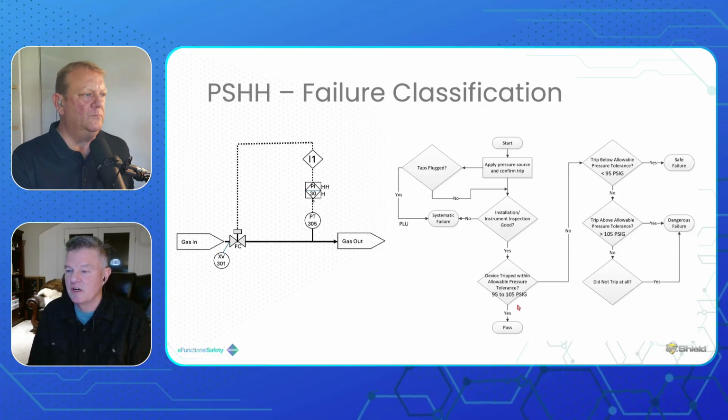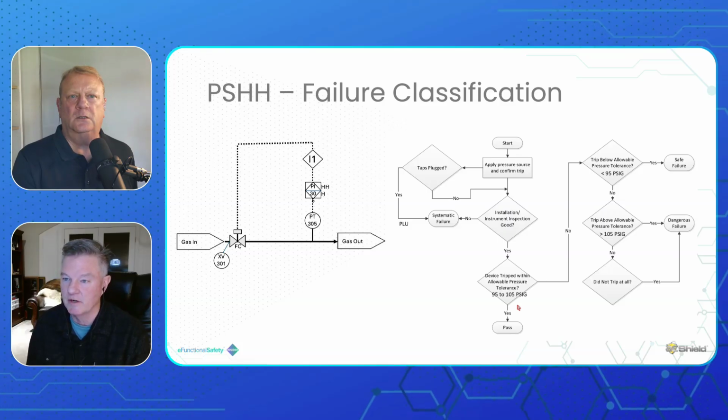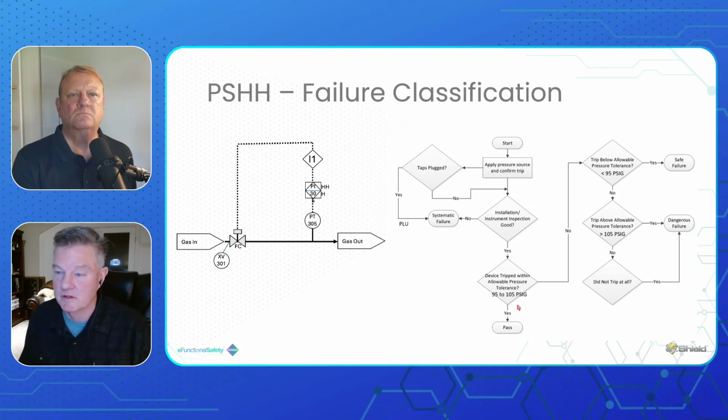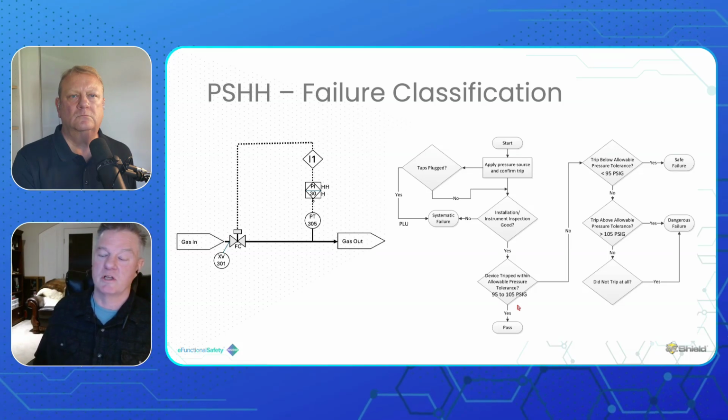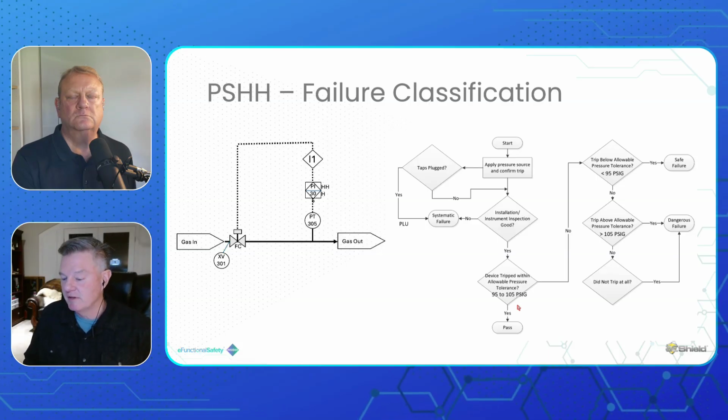So this is classification. Think of a valve, overly simplistic: what is it? It's got to close fast enough, right? If it's a high pressure close valve and the response time is 10 seconds, if it closes faster than 10 seconds, it passed. If it closed slower than 10 seconds, it failed. It's that simple. Not every valve needs tight shutoff.